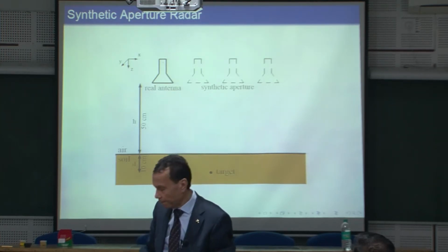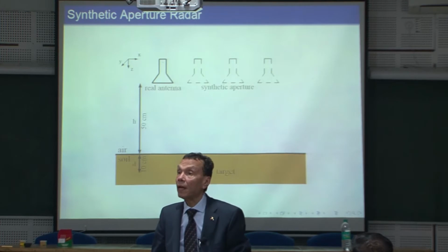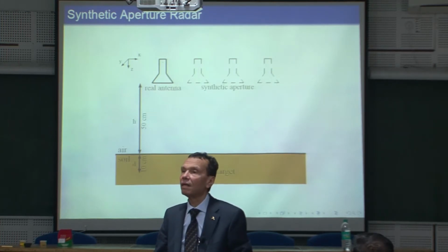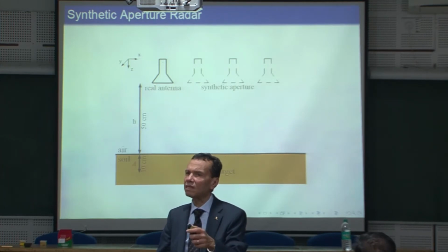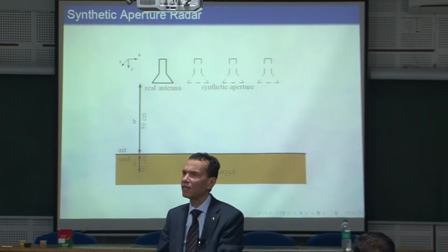No, of course, sure. When you do a calibration, let's say a full 2-port calibration, we do it on the coax plane. Then we attach another horn. What you're saying is we do a calibration if it is a waveguide system. It's much easier to do with a waveguide. It's called multi-tier. So you can use, say, the standards of the network analyzer.